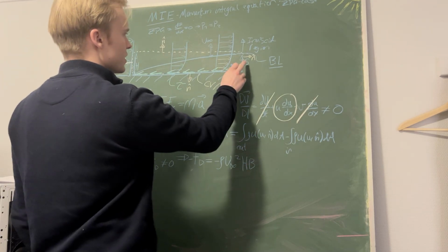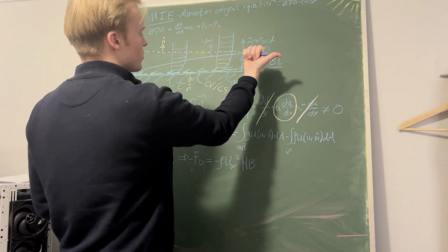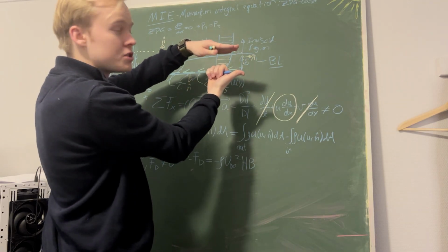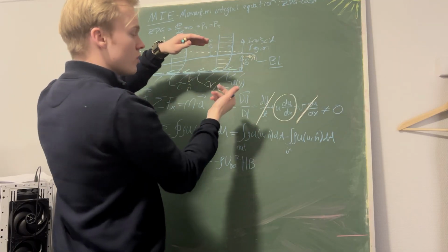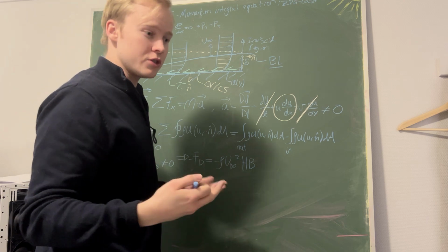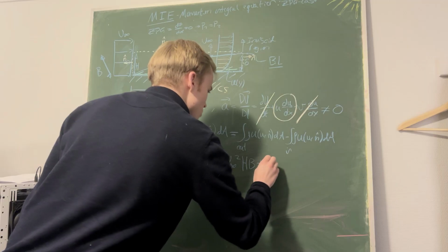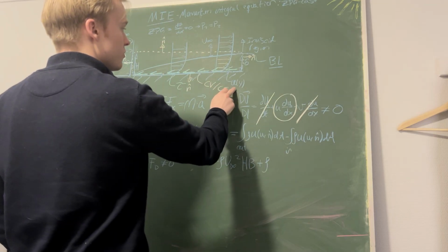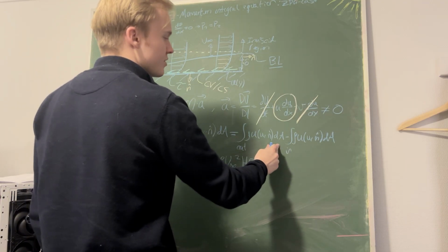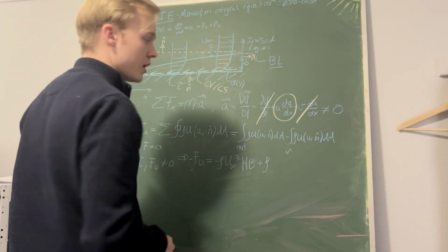And then considering our outlet case, well, the normal vector is pointing this way and our flow is going this way. So they are aligned, they're going the same way, which means that the dot product of u of y with the normal vector is going to be +1. Meaning that we're going to have rho, but now u is a function of y. So we cannot simply take this out of the integral and multiply with the area. We have to keep the integral, but we can move rho out because it's a constant.